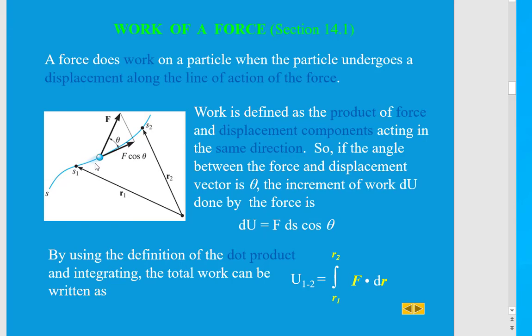Okay, so going back to the definition, if there is a force causing an incremental displacement from S1 to S2, then the differential work done by that force on that particle, which is dU, equals the force component F cosine theta multiplied by that ds.